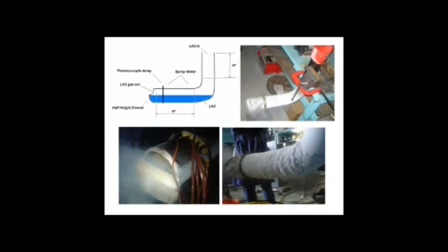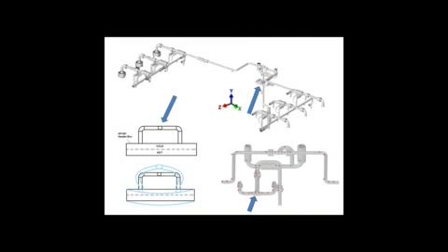What happens is you get a buildup of something in the bottom and something else on the top, so you get a circumferential heating pattern and bowing. The biggest condition where bowing occurs is in API 661 header boxes. The figure in the bottom shows you what happens as the box gets cold on the top and hot on the bottom. Just like a thermostat, it bows and it will collapse or crush the pipe on top.